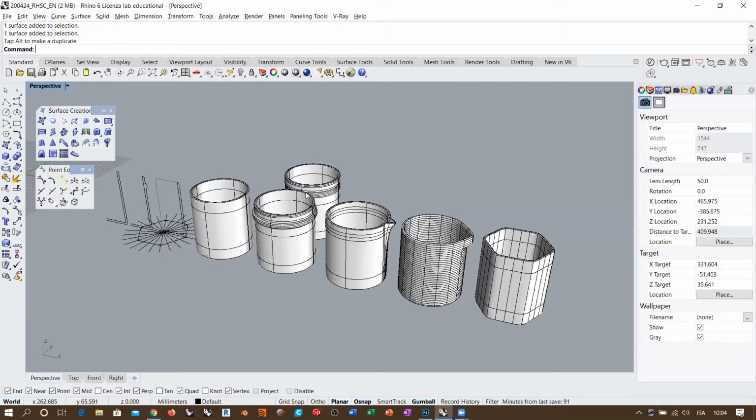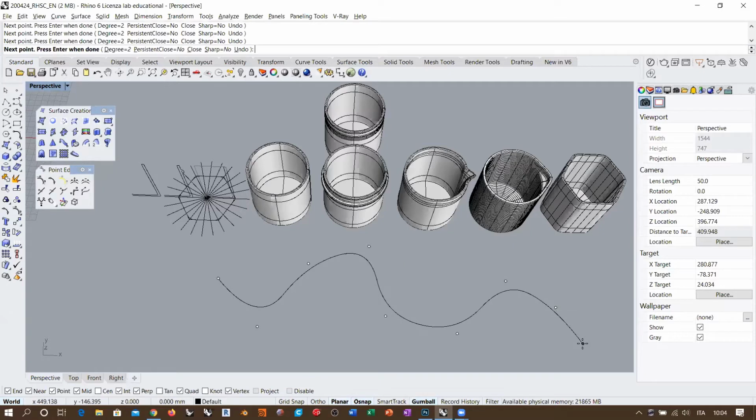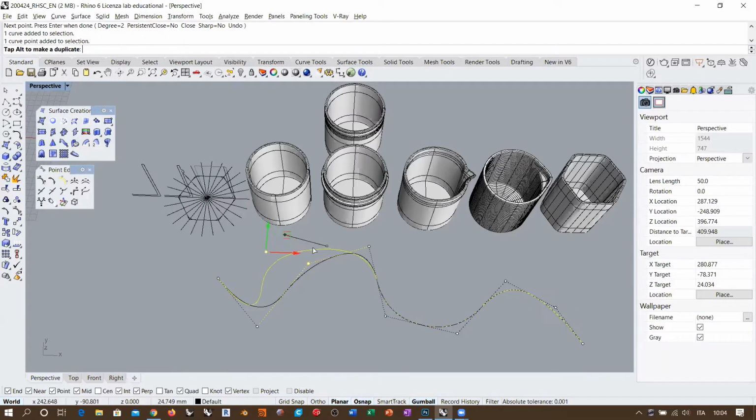But if you work, for example, with a degree 2 NURBS curve like this one, and you start placing your control points like here, you still see that the control points don't lie on the curve. So if you take this point here and move it around, you get no kinks along the path, right? So the problem with the circle is that it is not a standard degree 2 NURBS curve. It's a very particular degree 2 NURBS curve.